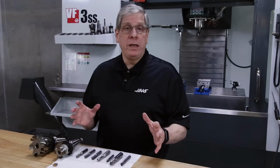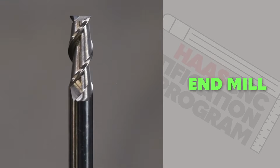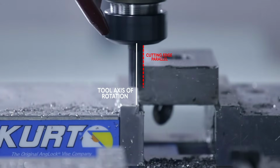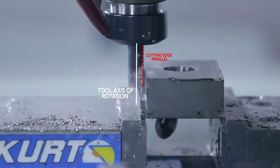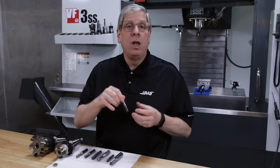Now let's look at milling cutters. The most common is called an end mill. An end mill rotates on its center axis like a drill, but it's primarily designed to cut with the side of the tool so that the cut surface is parallel to the axis of rotation. Some versions of this tool can cut vertically like a drill, but they're not as efficient in doing so.